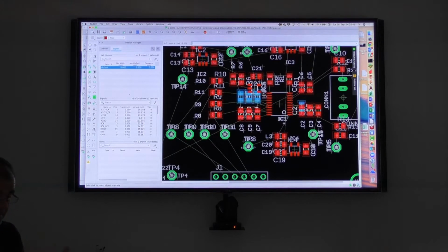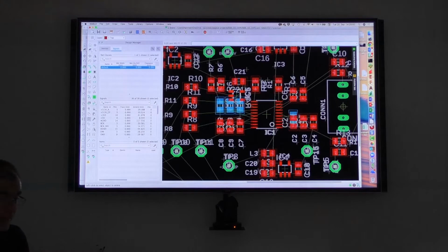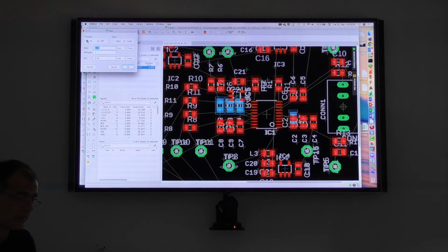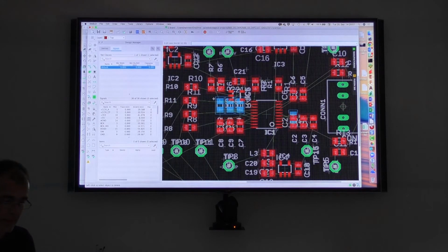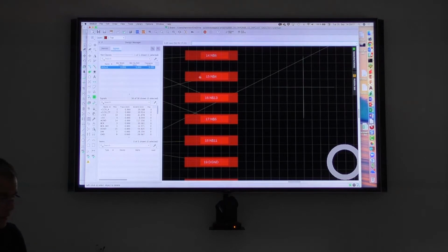Now I start with the root command, and here again think about the grid. I have here 1/4 millimeter, I don't know, I switch on the grid display and then I check the positioning of my components, and this looks, yeah, not very well aligned. I think you have seen it's working, but if it's critical, we should think of moving